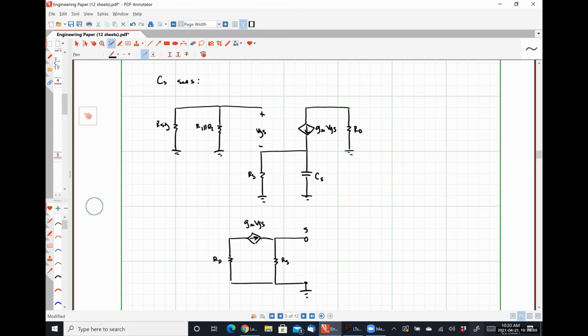So where is my voltage VGS going to go? Let's think about that. Yeah. The negative polarity terminal is tied to my source, and the positive polarity terminal, it should be pretty obvious, is tied to ground because there's no current flowing through any of this parallel resistor combination, because there's no independent source pushing current through it.